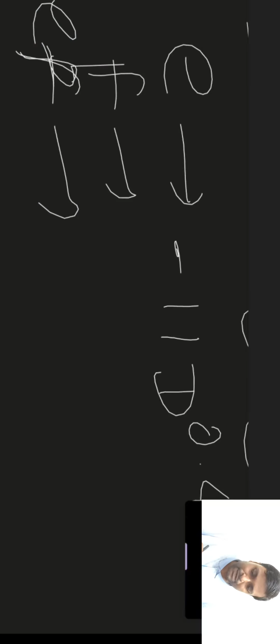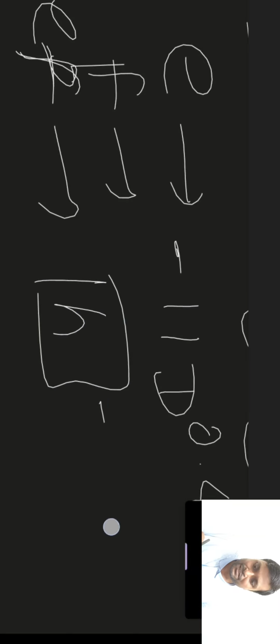So what will be the fundamental deviation for an h shaft? This is the zero line, and this is the h shaft. This is the fundamental deviation, the deviation which is nearest to the zero line, and this matches with the zero line. So the fundamental deviation for this h shaft is 0.